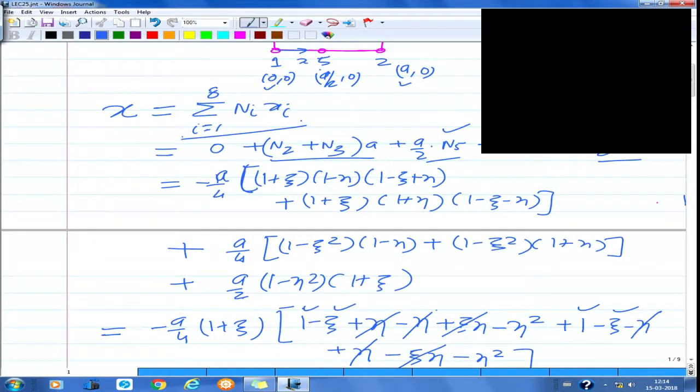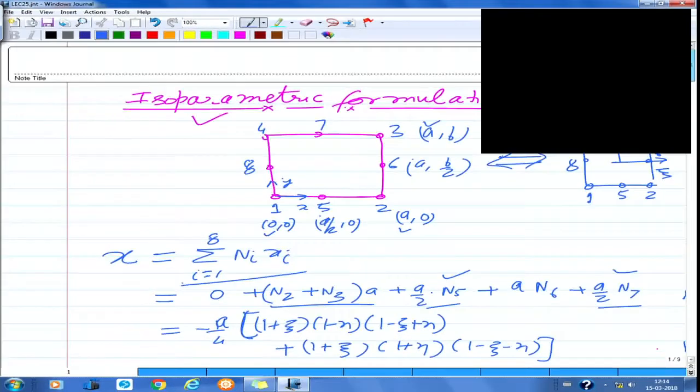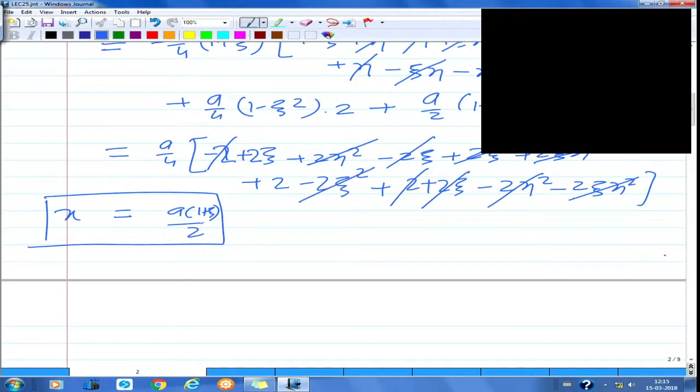So we got this. So our initial assumption is that, but since the element shape in the physical coordinate space is a rectangle, here you will find that automatically you get x as linear in xi, although your variable, depending on say temperature or displacements, will come out as quadratic within the element. Of course, even if the solution is also linear, then it might turn out to be linear. So you would see that finally what we have is x is linear in xi. Same way, if you look at y equal to sum of Ni yi, with i going from 1 to 8 for the 8 noded element. And why did I take 8 noded? Because here you have quadratic.